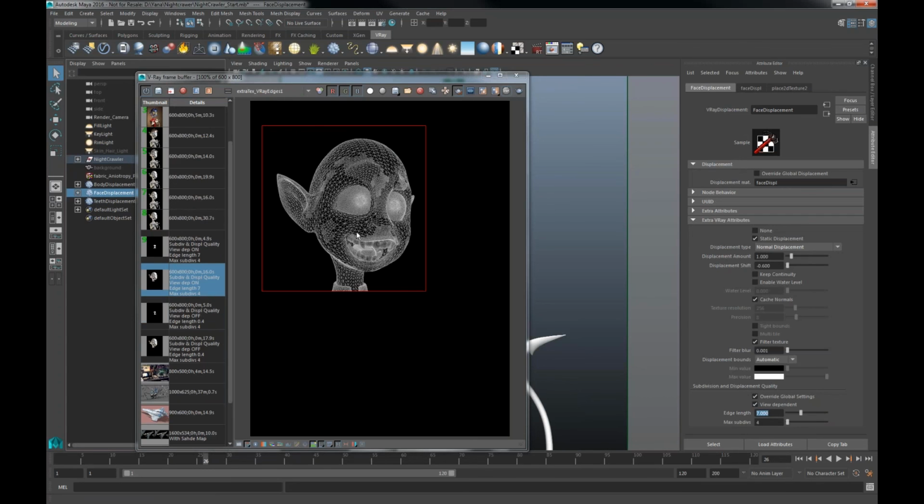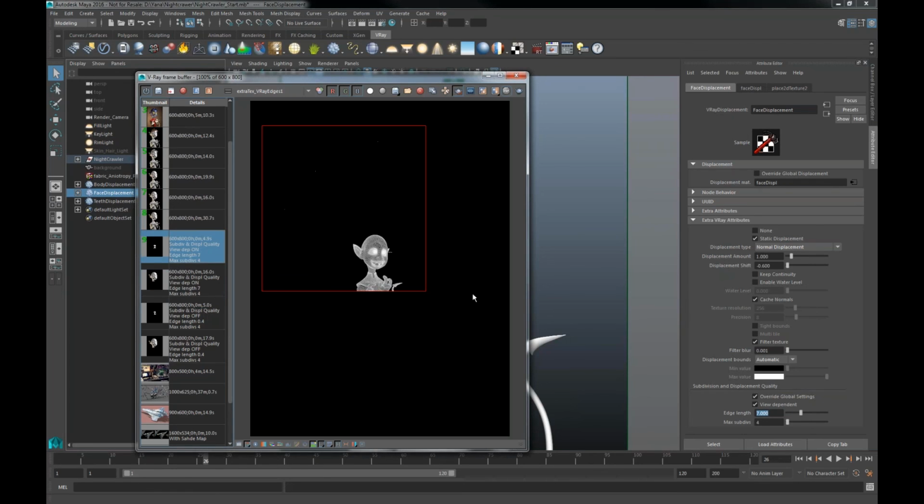And let's see what's going on when the subject is far away from the camera. So here you can see that I don't have so much subdivisions because again the edge length will be measured and it occupies less than 7 pixels in this case. And using this approach, you save time if your object is away from the camera, because V-Ray won't subdivide it, because it won't be necessary.